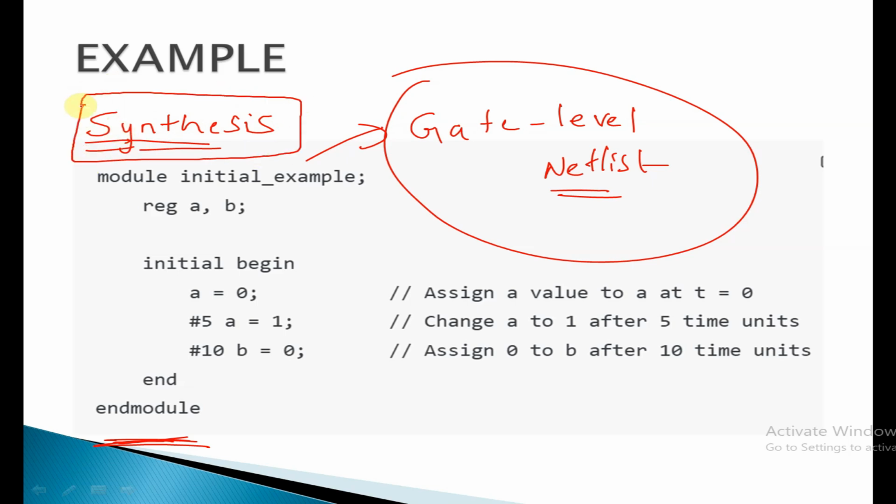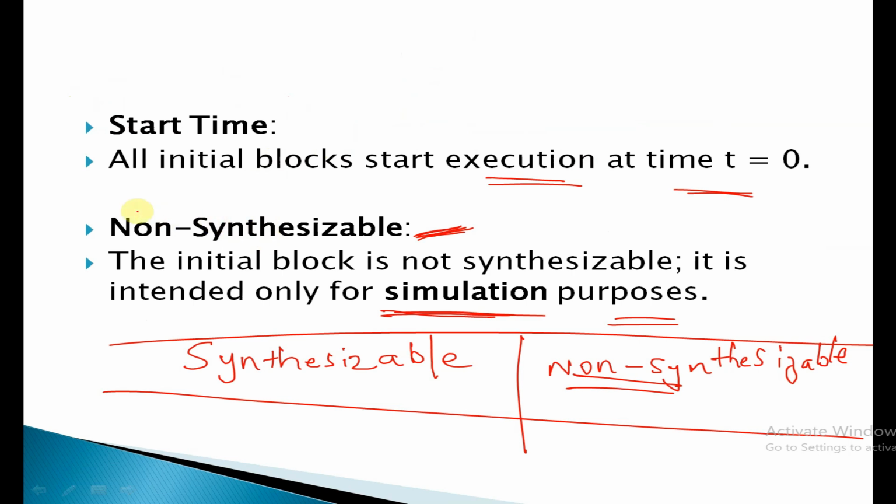So basically in Verilog we have two types of constructs: synthesizable constructs and non-synthesizable constructs. If you use non-synthesizable constructs, then your particular design is not going to synthesize. That is, your code is not going to be converted into hardware. So you should be very careful when you are using these non-synthesizable constructs in your coding.